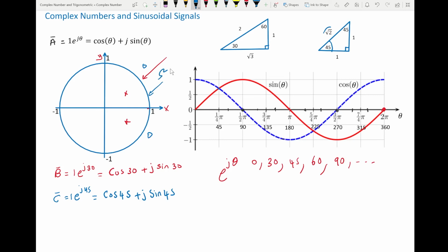So if I want to know what's the system response to a frequency located here, that could be omega 0.3π, in this case, the system response will be the length of the vector from this zero and this zero to this point. So that will be R1, R2, divided by the length of the vector from the poles to this frequency of interest. And this is D1 and D2. So the system response will be R1 times R2 divided by D1, D2. Basic concept of complex and sinusoidal help us to understand how the system responds to different frequencies.